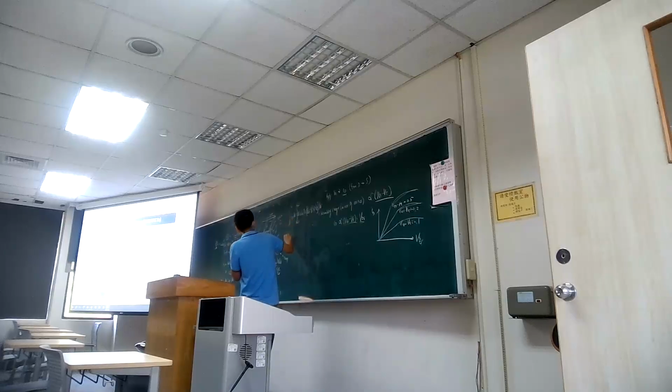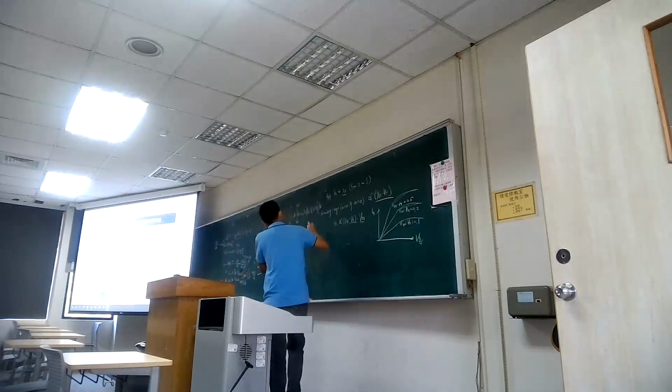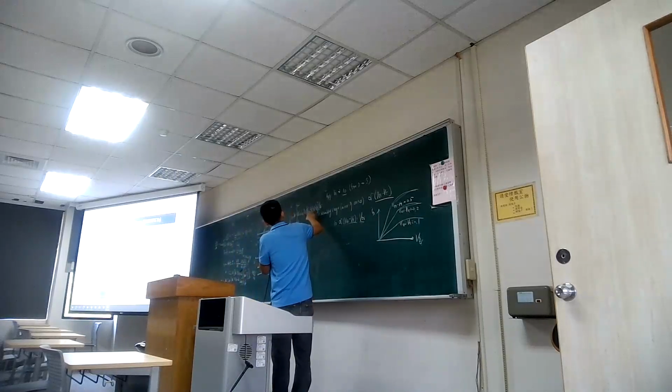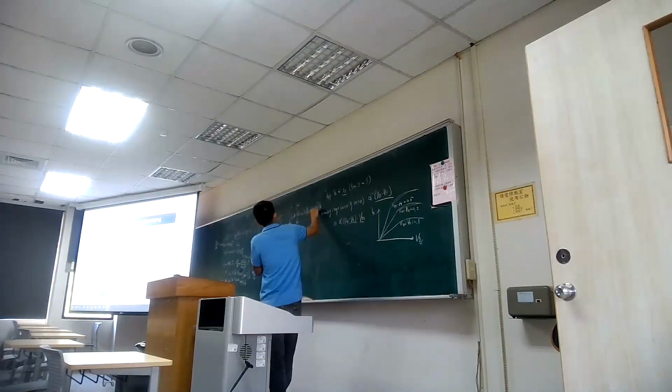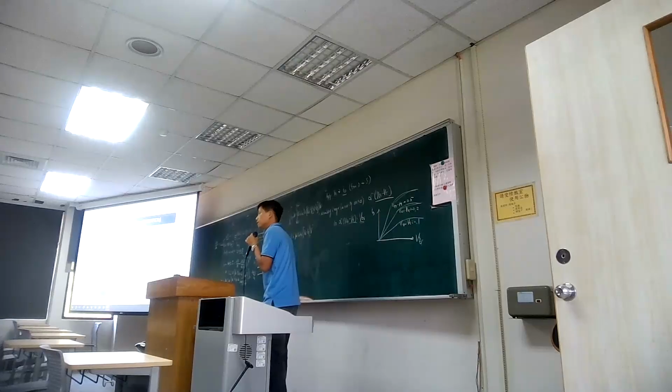Okay. So the left side is simple. It is linear. So ID multiplied with L equals the integration of the potential, with μn, Cox, and W outside. Okay. So there will be only one factor which is x dependent, right? Only this one is x dependent. The other two seem to be just a regular product, VGS minus VT. So you get a VL. So what is VL? VL means VDS, how much voltage we apply from drain to source. So this one we get a VDS.